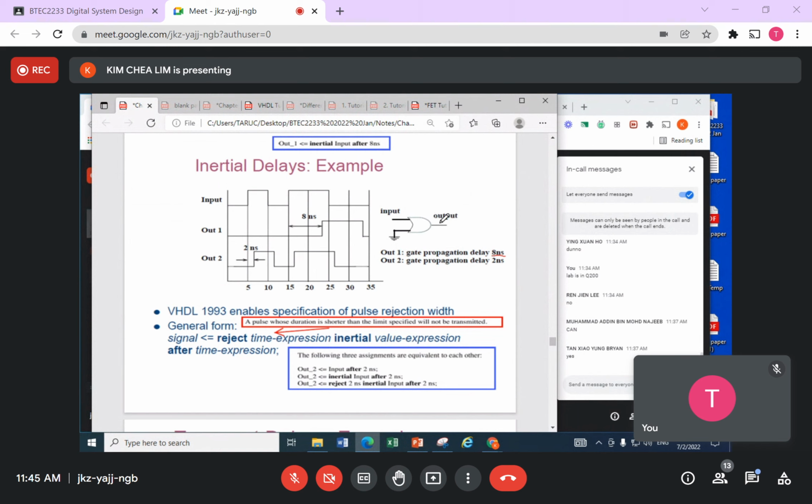That is to say, to get the output correctly, it must be 8 nanoseconds later after receiving the input. In this example, one input is directly shorted to ground, so it is level 0, no problems. So it is the other input that decides when I am going to get the correct output.